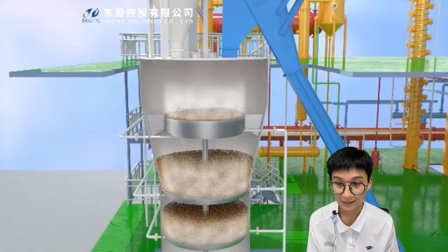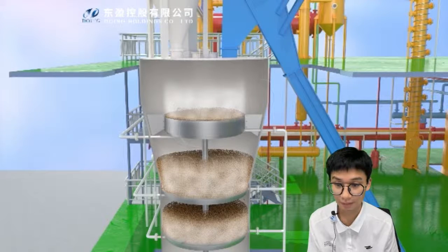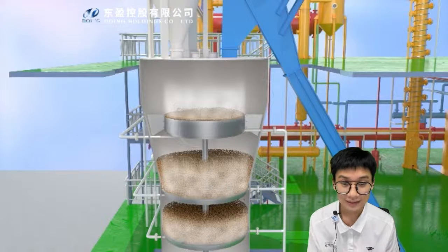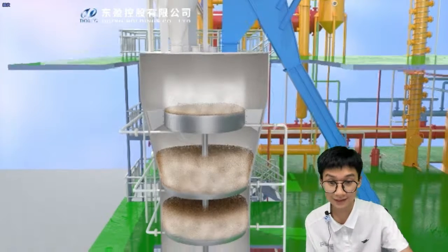As for the last, the baking layer, also known as the energy saving layer or flash layer. The baking layer is located under the direct steam layer. There is a vacuum device. The main purpose is to recover and utilize the residual steam of the direct steam stripping meal. Each layer is equipped with a pair of stirring fans, and in addition to the pre-desolventizing layer, which discharges through a normal opening door, the other layers use a rotary valve or winch to control discharge and material sealing. This is our DTDC.